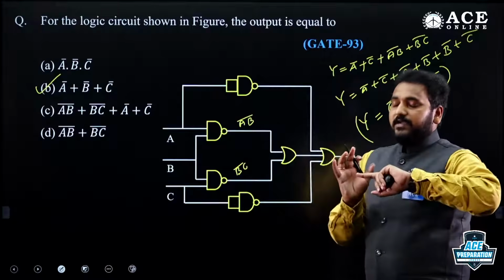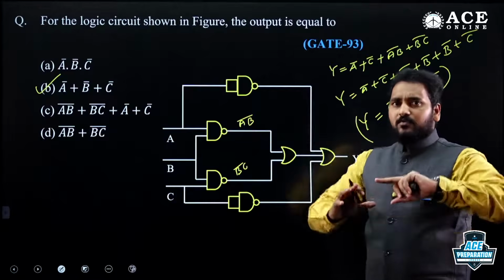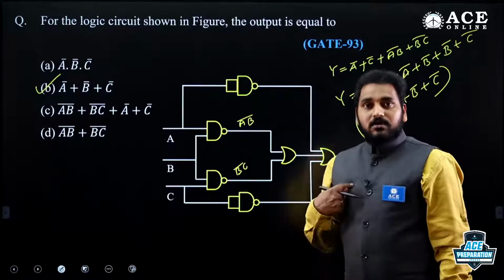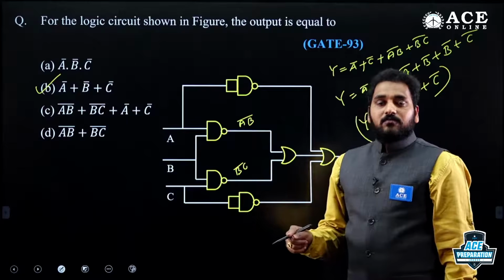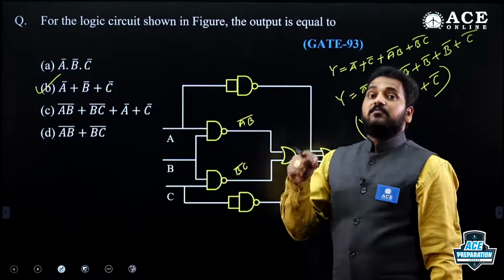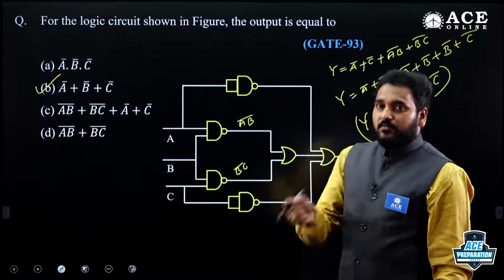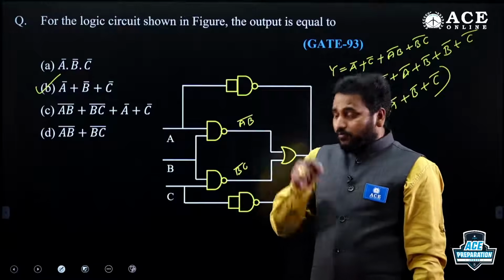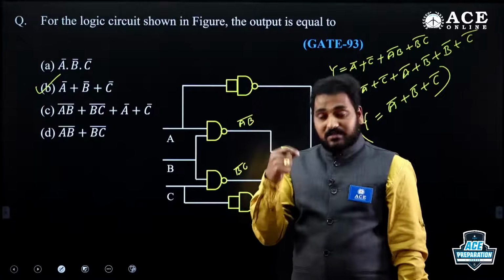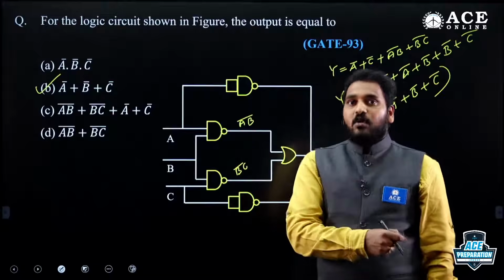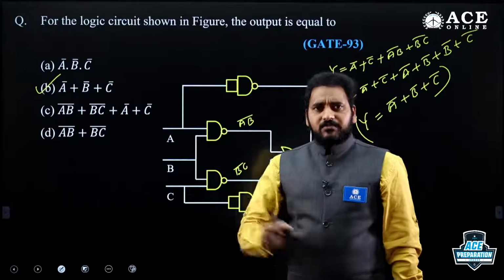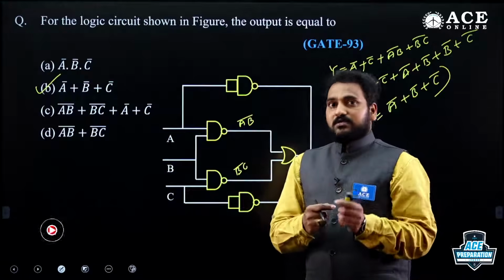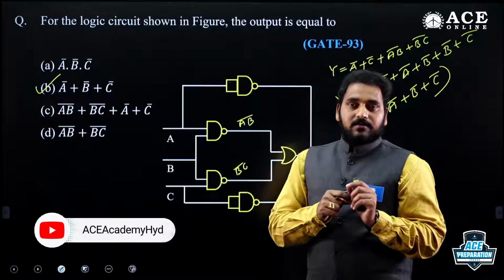Like that, if I find counters is a very important topic, so I want to go for the counter. Immediately if I go for the counter, can I understand? No. I should learn what is a flip-flop, what is a latch, how to interconnect flip-flop and latch, what types of flip-flops we have: D flip-flop, T flip-flop, SR flip-flop, JK flip-flop and so on, and their truth tables. What type of trigger, I mean clock excitation, has to be used in the counters, level trigger or edge trigger. If I come to know edge trigger, there are two types, positive edge and negative edge, and how it will work for the excitation of the clock.